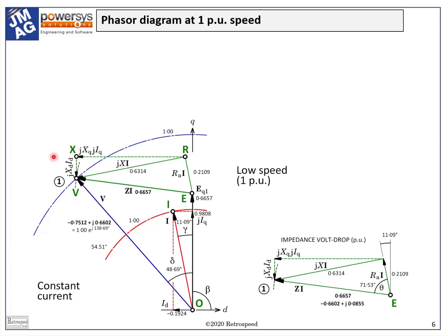The difficulty with this is that saturation makes a complete mess of the inductance matrix, regardless of the frame of reference. Blondel's so-called two-reaction theory sidesteps this mathematical can of worms, while still retaining the ability to deal with bulk saturation in the d and q axes. These ideas were not only known in the 1890s, but put into practice in design offices in more or less the same way that we do today.